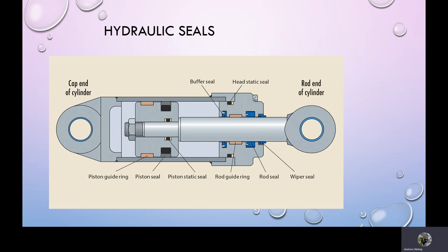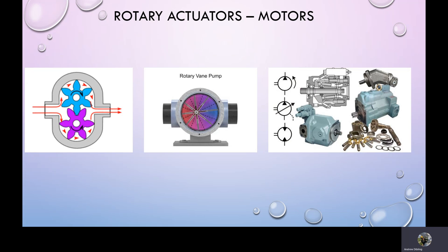And you'll find those, I bet, on different types of equipment, especially mobile equipment working in dirty environments, to try and keep the system clean. And it's very important that those systems be kept clean. Otherwise, the contaminants getting into the hydraulic system can ruin pumps, directional control valves, flow control valves. Because remember, inside your hydraulic system, even though it may be a 1/2-inch line going to that cylinder, there are teeny tiny little passages that are not very large that the fluid has to go through.